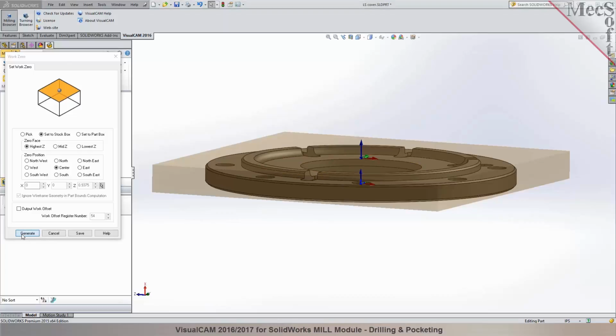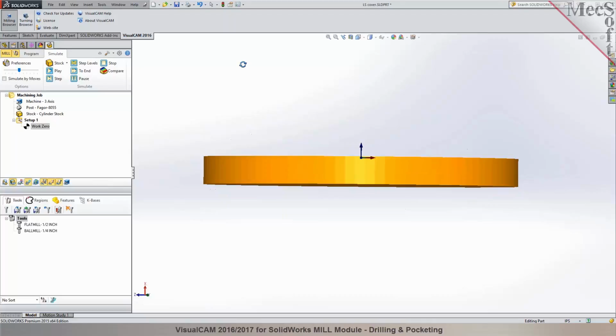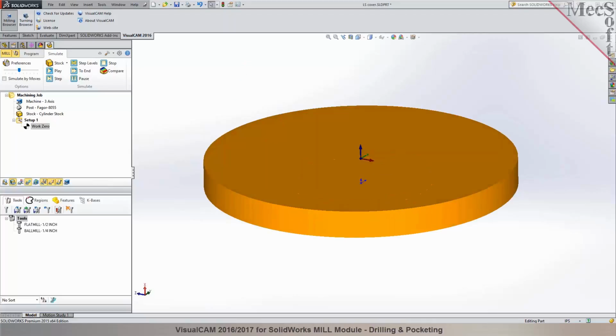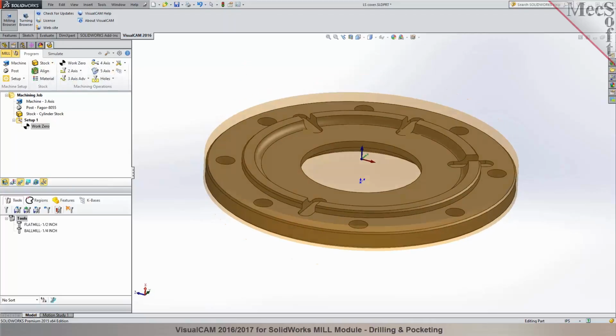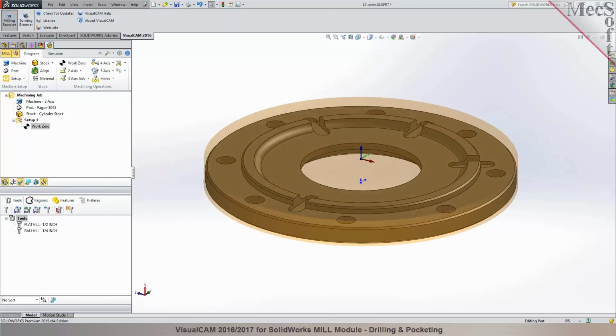Would you prefer to put your XYZ origin right at the top and center? No, that's fine. Center is okay. Okay, top of the stock blank and then the center, right? Yeah. Okay, we are now ready to program toolpaths for it.